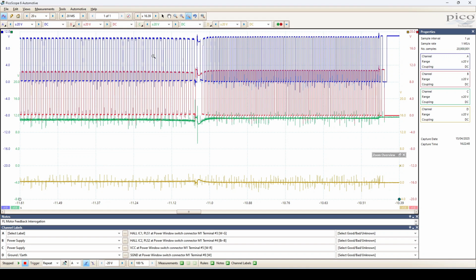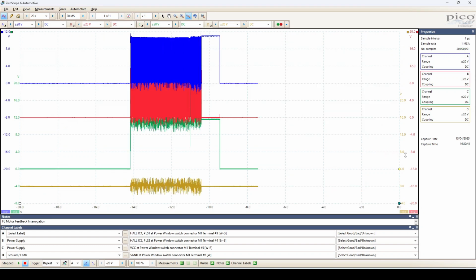And when it sees the speed of the motor slow down, because these are high torque motors, you can hurt someone. An adult maybe not, but a child definitely will do a lot of harm to a child's hand. So when the computer sees the velocity of the motor slow down, it backs off the motor and reverses the direction and then stops it.